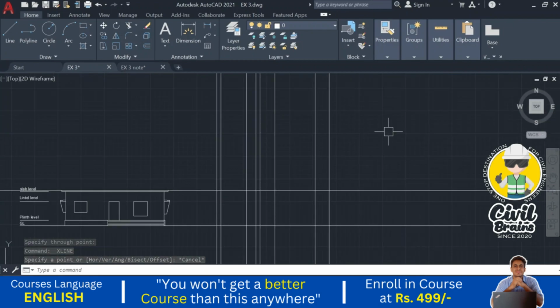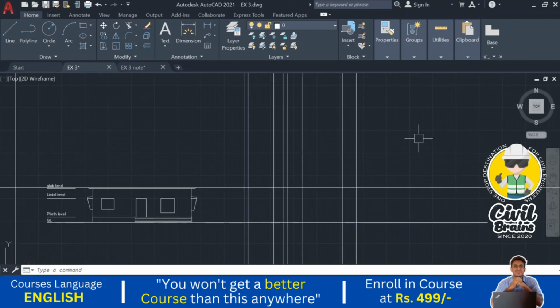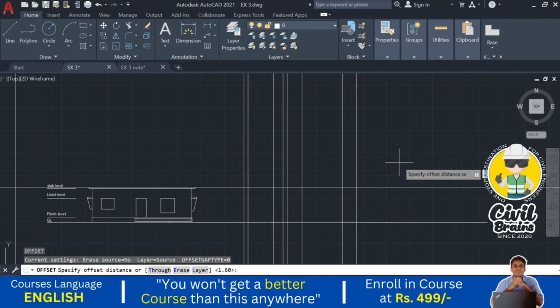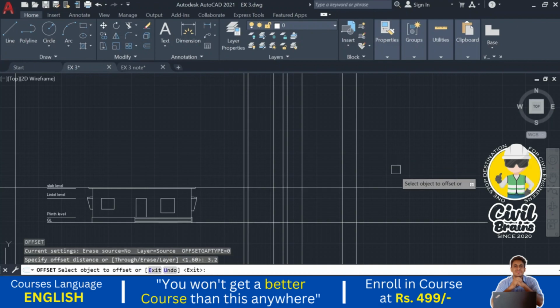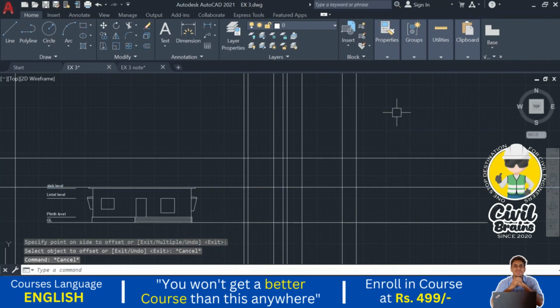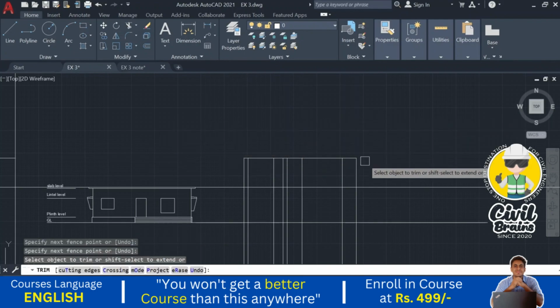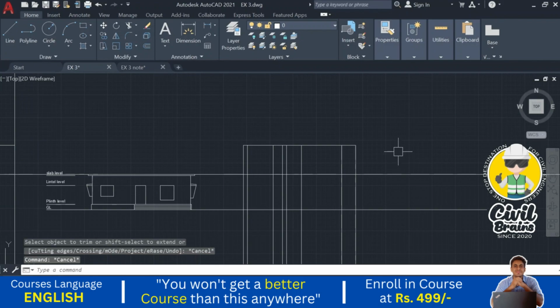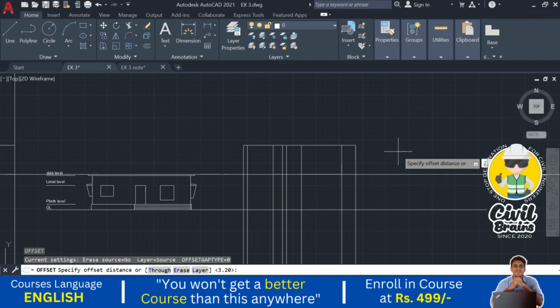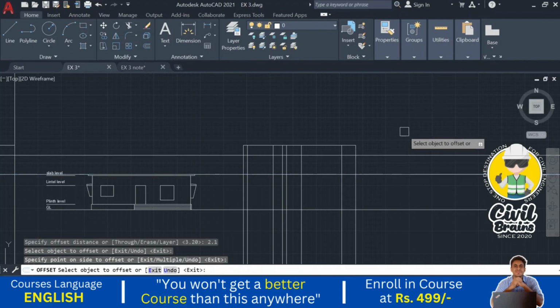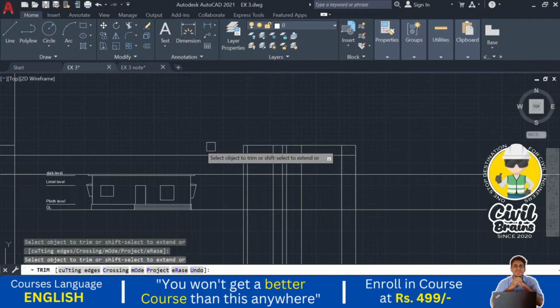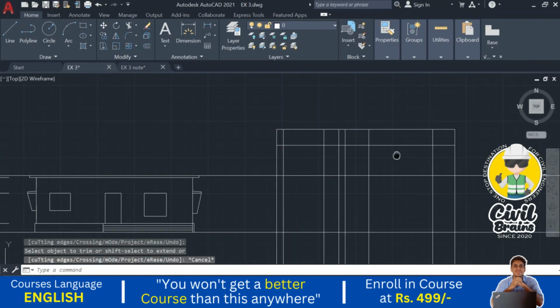So what is the height of the first floor slab? The same height we have maintained for the first floor slab also, that is 3.2 meters. So I draw offset 3.2, enter, 3.2, enter. So this is our slab. I just trim this one, extra parts we don't want, so you don't get confused here. What is the lintel height? 2.1 meter. I just offset 2.1 meter. So two levels I have drawn here, lintel level and this one.